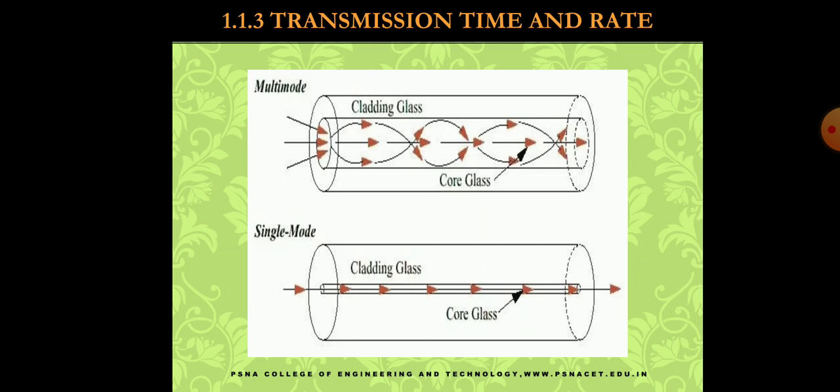While single mode fiber cables often use a laser or laser diode to produce light injected into the cable. The commonly used single mode fiber wavelengths are 1310 nanometer and 1550 nanometers.